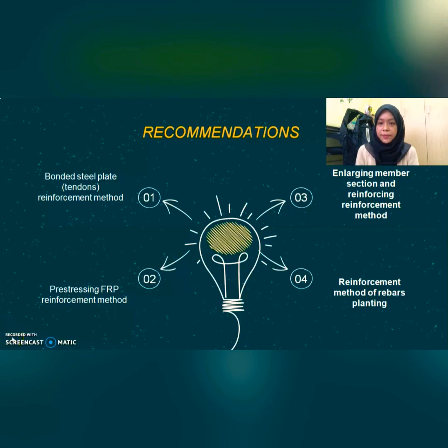Fourth, the reinforcement method of rebar planting. Epoxy for rebar connection and heavy anchoring. Structural connection with post-installed rebar, for example, extension or connection to wall, slab, stairs, column, foundation. Then, structural renovation of buildings, bridges and other civil structures. Retrofitting and re-strengthening of concrete members is possible. Then, anchoring structural steel connections, such as steel columns and beams.